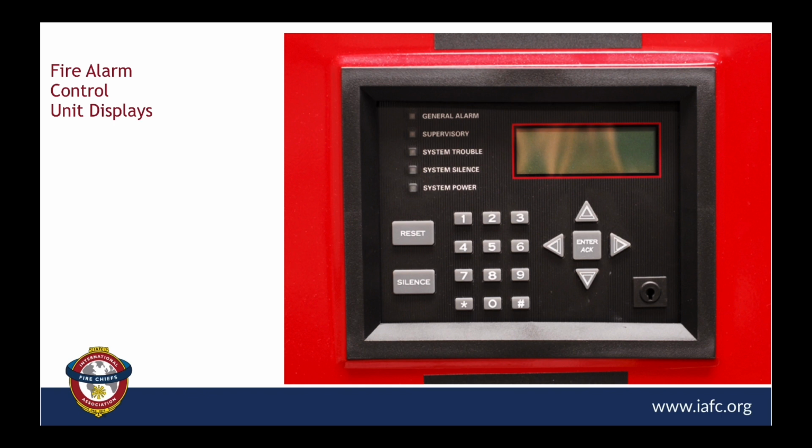has been detected. Now, when you walk in and you see the secondary light lit up, this one's called supervisory. As you'll hear in the next segment, when they talk about the different types of initiating devices, supervisory are those devices that are monitoring or supervising other systems, usually fire suppression systems. These are most commonly known as your tamper switches that are monitoring the open position of the water valves.